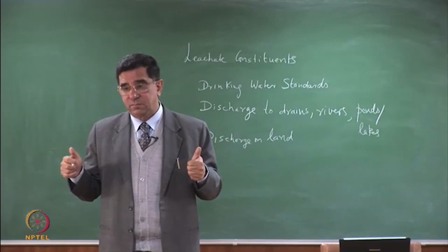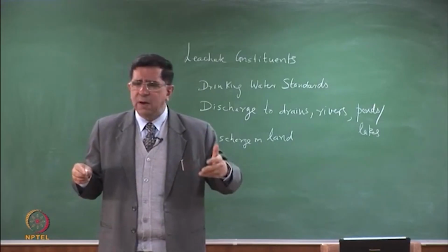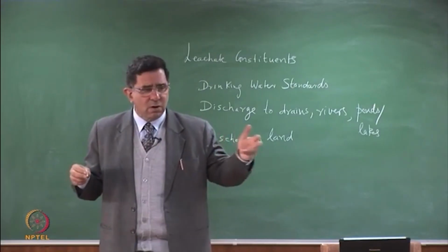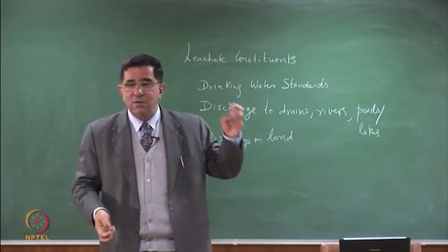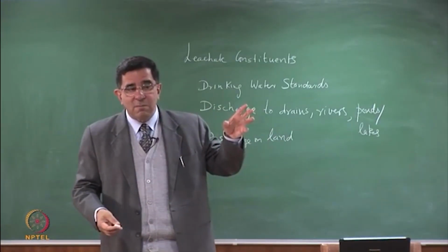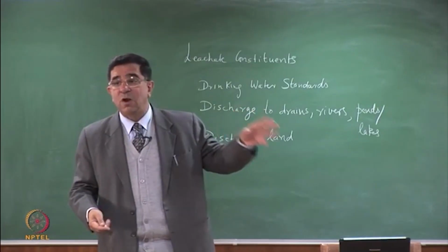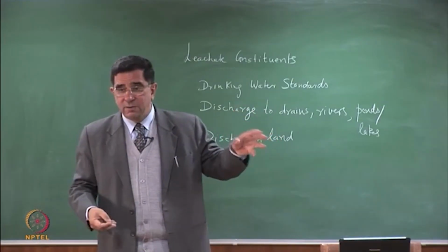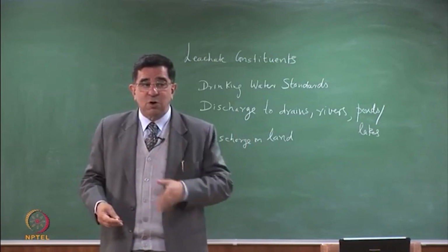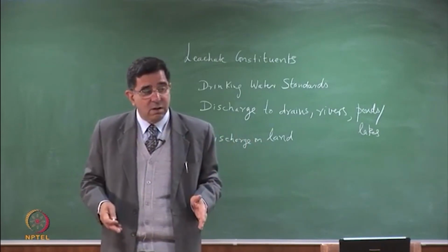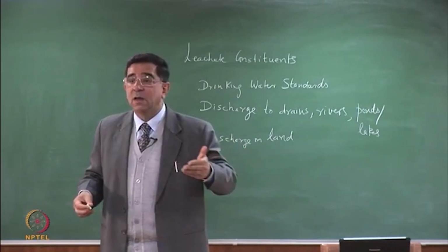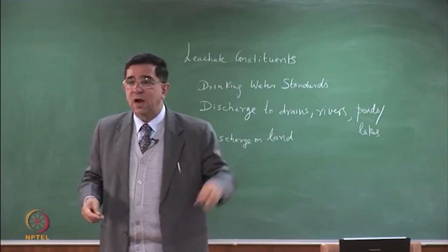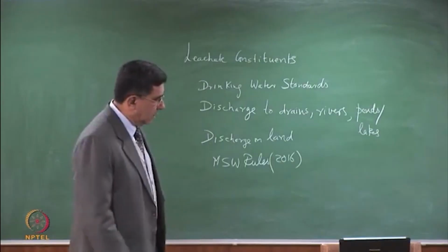You understand? Somewhere there is salty water, and somewhere there is drinking water. So if you have salty water, it means there is some high amount of total dissolved solids, right? So then your benchmark becomes that what you are putting on the land, which will go to the groundwater, should not exceed what is already existing, the background level. Okay.